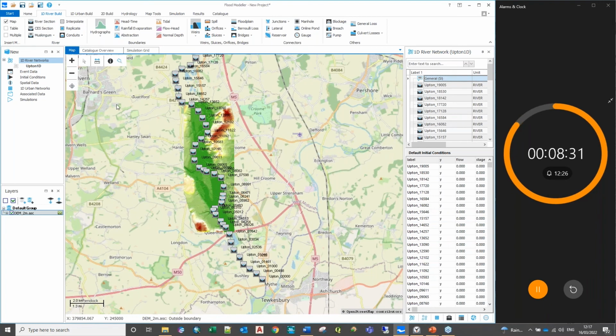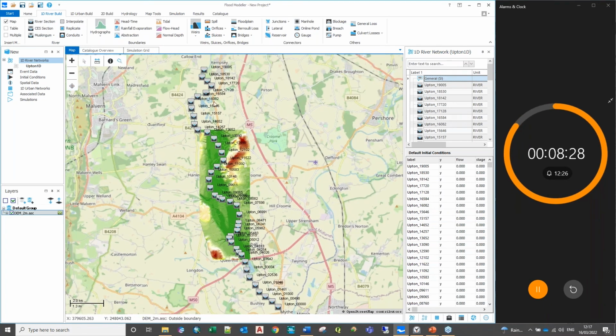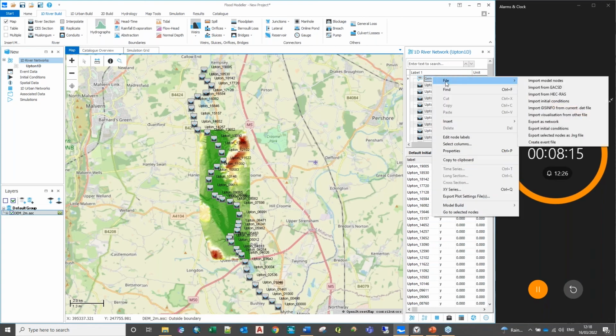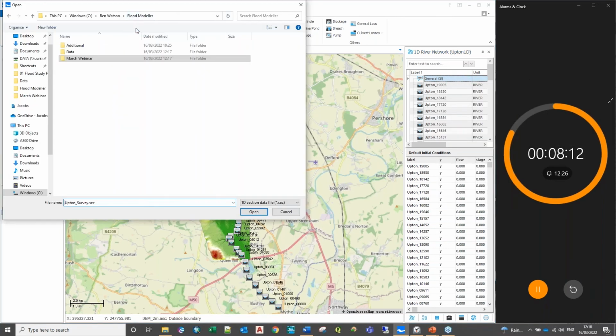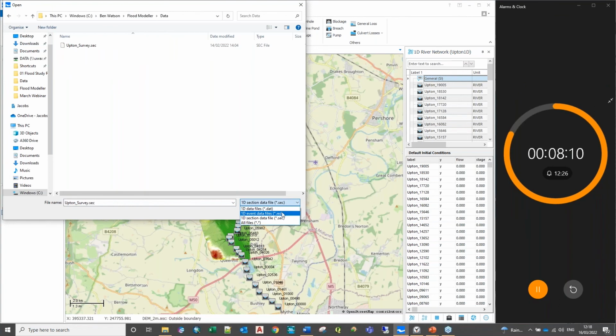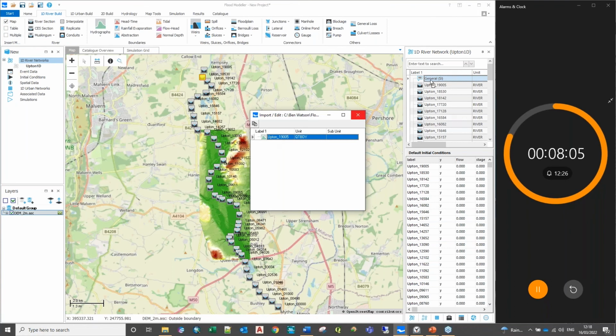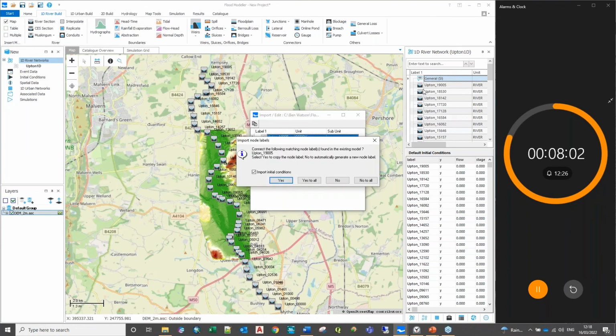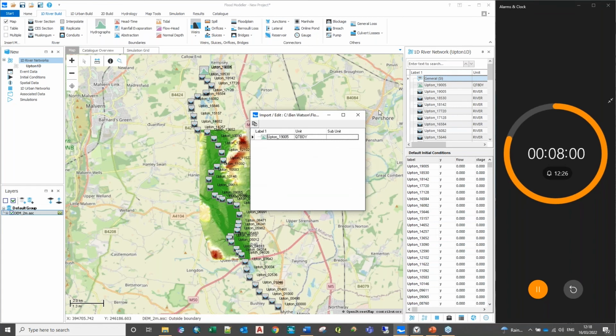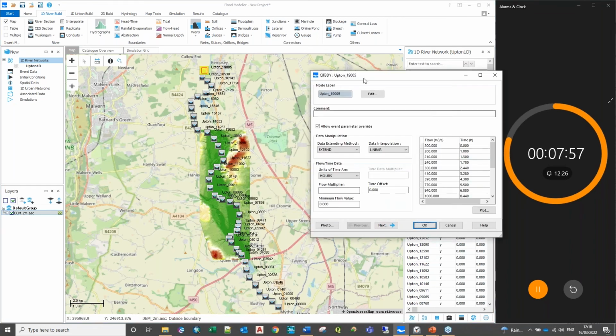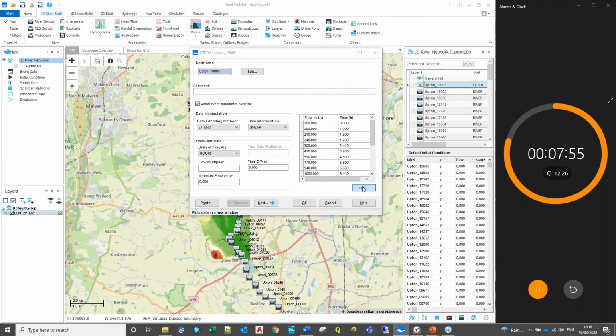We'll now create some inflows to the 1D model domain. So we'll go to the upstream model extent and import an inflow hydrograph in the form of a QT boundary. I'm being provided with an inflow unit from the hydrologists, so I'm just going to navigate to that inflow data. Select the IED, and again, drag across into the network window. We'll click yes to link to the upstream node. And then I'll just show the populated QT boundary and our inflow hydrograph there.